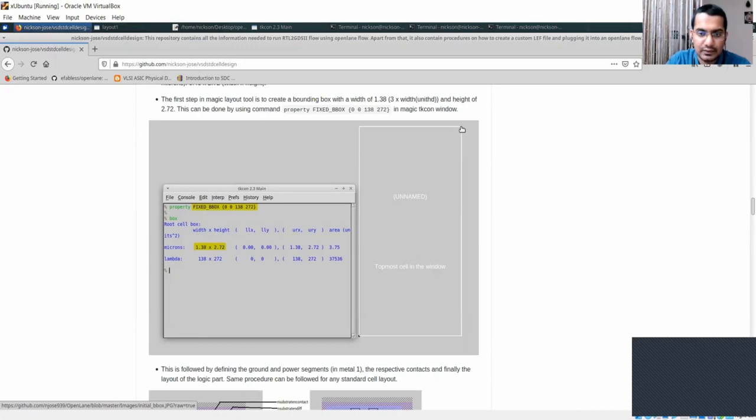Okay, and finally we'll use mask 16 to drill the contact holes and bring this particular contact outside your chip. And now this is how your CMOS 16 mask process will look. So you have your contacts, you have your source, you have your gate over here, you have your drain over here. Drain is connected right from this point and reaches till this point. You have your source over here, you have your gate over here, you again have your drain over here. So this was your 16 mask process, and this finishes the fabrication steps that we wanted to do now.